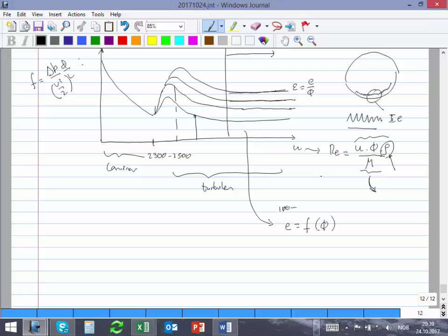He found the correlation, and came up with this equation that says the friction factor is just 0.0777 divided by d to the power of 0.224. This is for d in meters, but I can give you also for d in inches. And problem solved. Then I can insert that friction factor, which depends only on the diameter of the tubing, in my previous equation. Finished. It sounds simple. The equation has a lot of constants that you have to insert, but it's really powerful and really realistic. It really captures the complexity.